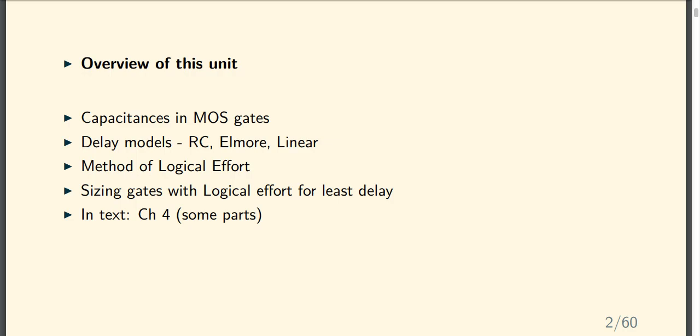Okay, so a few outlines of the topics in this unit. Most important source of delay in almost all digital circuits is capacitances, and that will be a very important focus of our unit also. So we have three components in almost all circuits: R, L, and C. And R is unavoidable. Every wire has a resistance R equal to rho L by A. And similarly, capacitance also we have learned, that you probably have learned. We will go through it again.